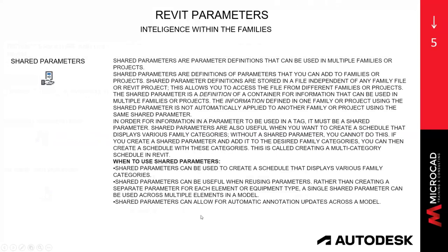And as long as this text is, that is as complicated as shared parameters are. Shared parameters are parameters that live on a text file outside of your model. It needs to be placed in a central location so that all the users in your organization have access to it. Revit can look at only one shared parameter file at a time. They need to be really thought about, organized and created.